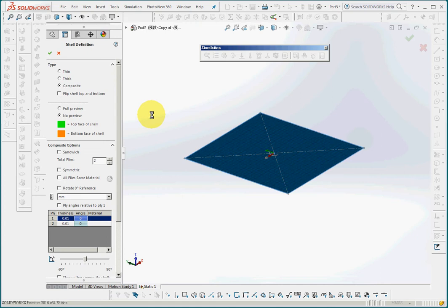So I'll go ahead and define composite. For composite material, I'll choose 8-layer composite, 8 layers. I'll define it as a symmetric composite. All panels are the same material. You don't have to choose this one, but for this case, all the materials are carbon epoxy composite. So I define material.